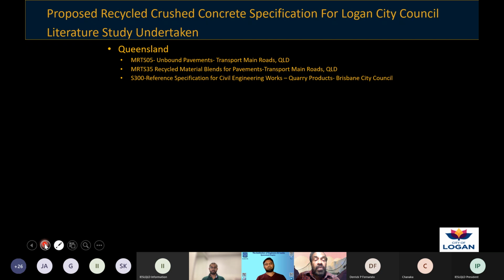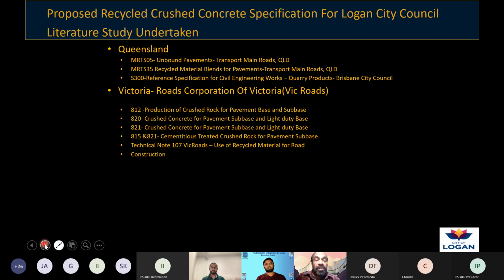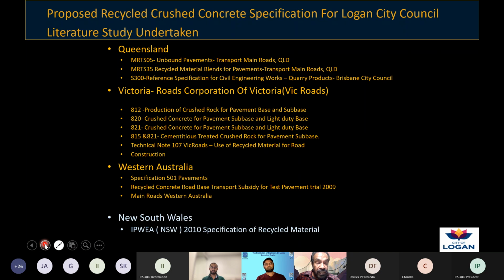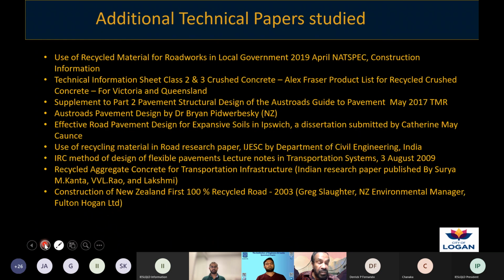A literature study has been undertaken. I studied the Queensland Transport and Main Roads specification, then the Victorian VicRoads specification, then the Western Australian one. Finally, I studied the New South Wales IPWEA specification 2010 for recycled crushed concrete material. Then I studied a huge amount of other literature from around the world, from India, New Zealand and many other countries. Finally, I came out with a suggestion to use the IPWEA New South Wales specification to suit our standards in Logan.